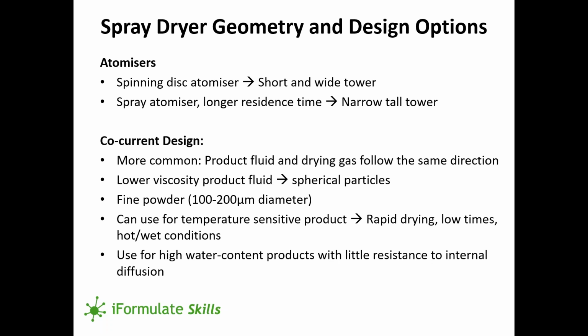Now, an advantage of this kind of design is that you've got fine particles that dry relatively quickly. So you've got rapid drying, a low time in the dryer, and relatively hot and wet conditions. You're getting all of that energy going into drying the droplet and not heating the particle up. And so it can be used for temperature sensitive products. And you can use it also for high water content products with little resistance to internal diffusion.